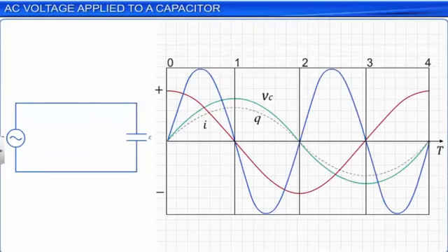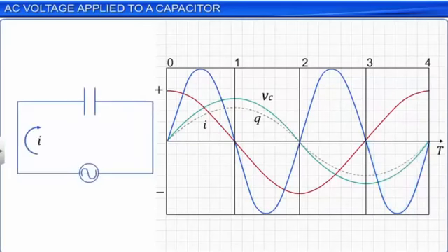As shown in the graph, we will study the charging of the capacitor in the 4 time periods marked as 0 to 1, 1 to 2, 2 to 3, and 3 to 4 respectively. In the first time interval, 0 to 1, the value of the current keeps decreasing in the circuit from being maximum at time t is equal to 0 and reaching 0 at 1, at 1/4 of its time period. By the end of this time segment, plate A gets fully charged with positive charges and plate B with negative charges, and they oppose any further current in the circuit. The plates are fully charged at the instant 1. The voltage across the plates is in phase with the charge Q and peaks at time t is equal to 1. As the current and voltage are both positive, it means that the power is positive.